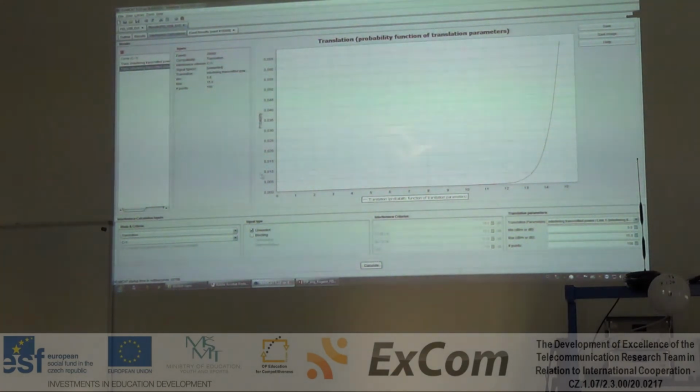So to have an interference probability of 1%, what should be the power? You can check here, it's around 13.5 dBm. So here you could give an answer to the regulator saying, okay, in order to have an interference of 1%, the interfering transmitter should decrease its power from 30 dBm to 13. Okay? This is the only way.